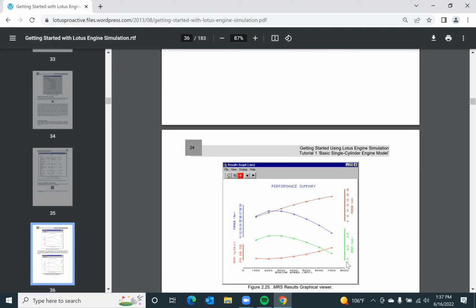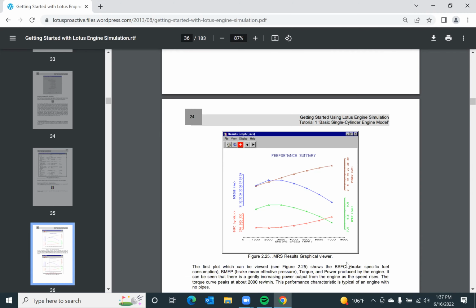That doesn't mean that the engine won't be able to operate all the way up to 7000 RPM, but as a designer, you will not recommend the engine to be operating in this region. That's why you have that red line on your internal combustion engines or cars. And that is where the engine is going to start making those strange sounds. Everyone understood this?